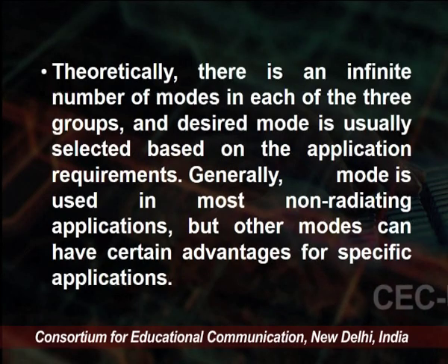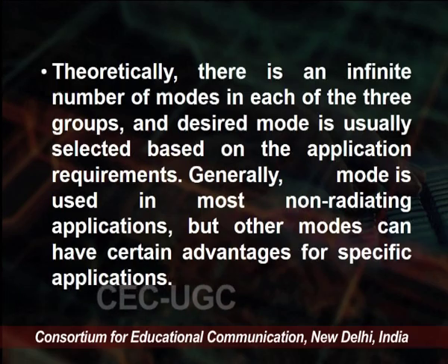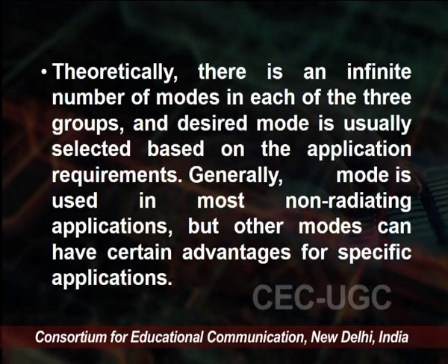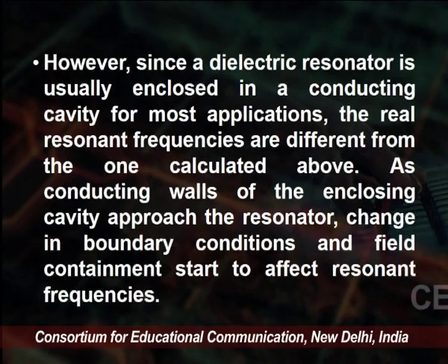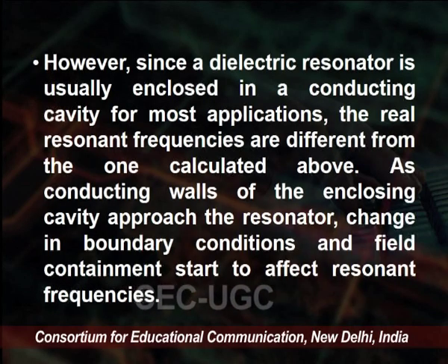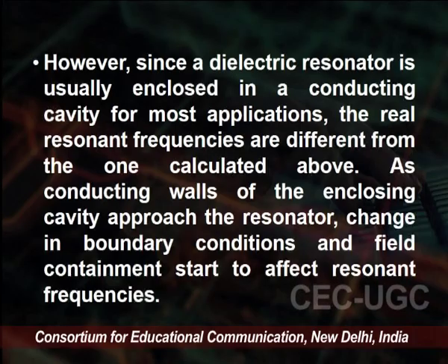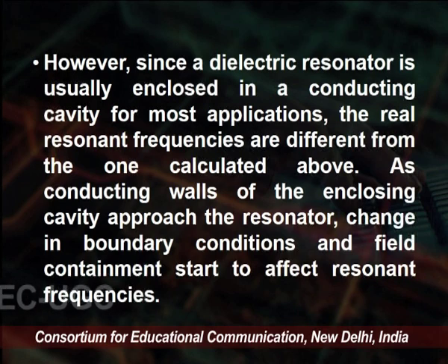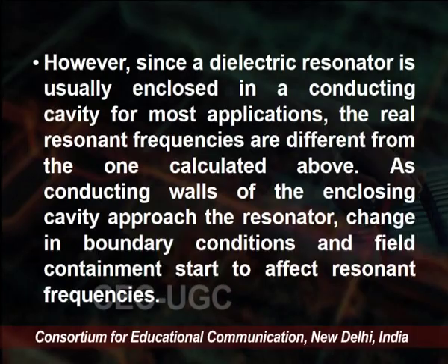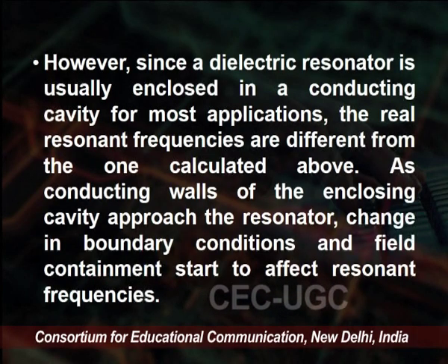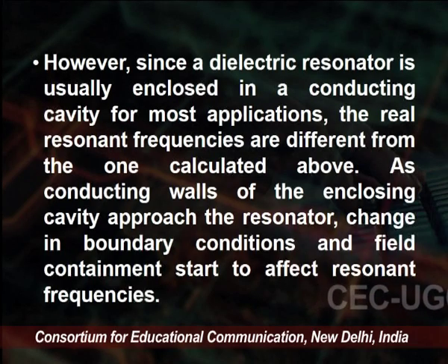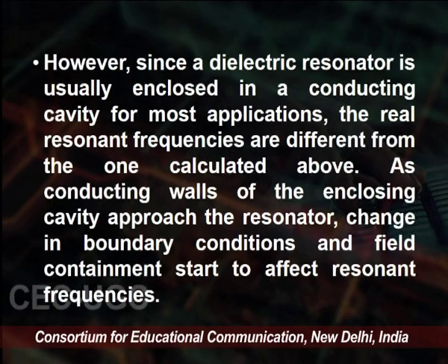Generally, one mode is used in most non-radiating applications, but other modes can have certain advantages for specific applications. Since a dielectric resonator is usually enclosed in a conducting cavity for most applications, the real resonant frequency is different from the one calculated above. As the conducting wall of the enclosing cavity approaches the resonator, it changes the boundary condition, and the field containment starts to affect the resonant frequency.